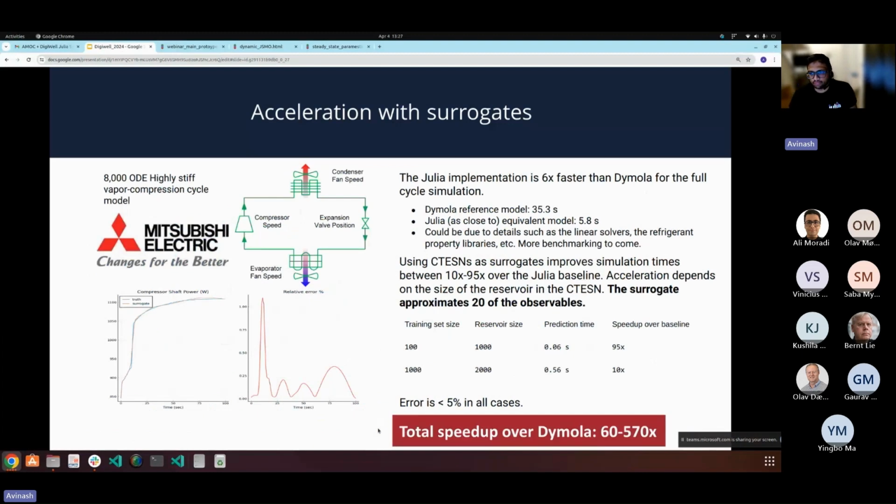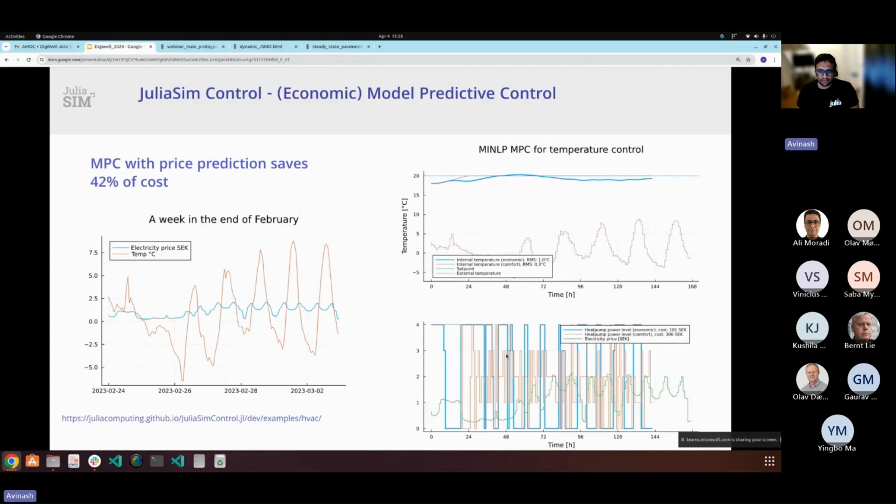The other idea is to perform acceleration with surrogates. So we have this digital echo, and again, one can pass in an FMU or a ModelingToolkit model, and once enough data is generated, we are able to perform acceleration. For instance, in most cases we get line over line models compared to the ground truth, with usually 1 to 2 orders of magnitude speed up, especially over FMUs.